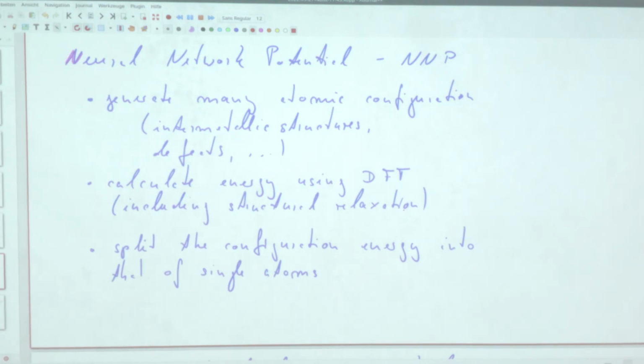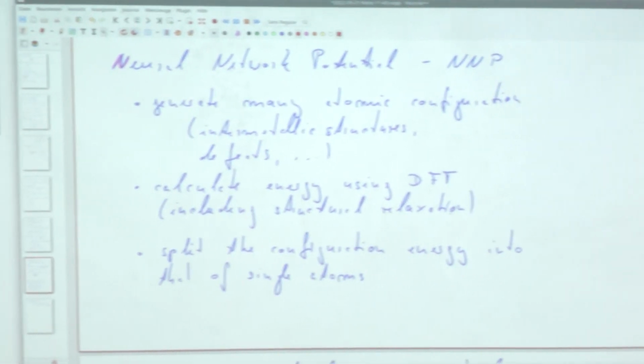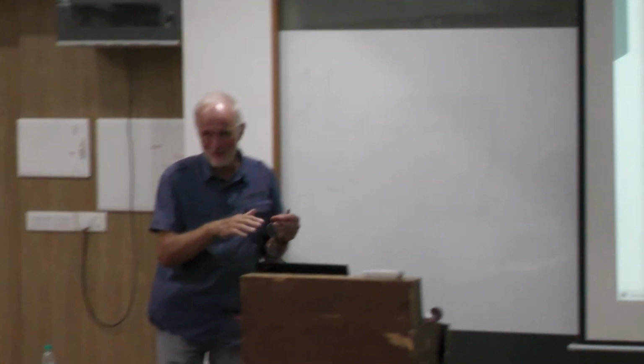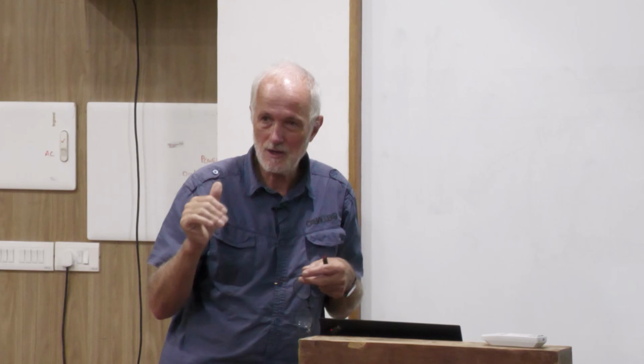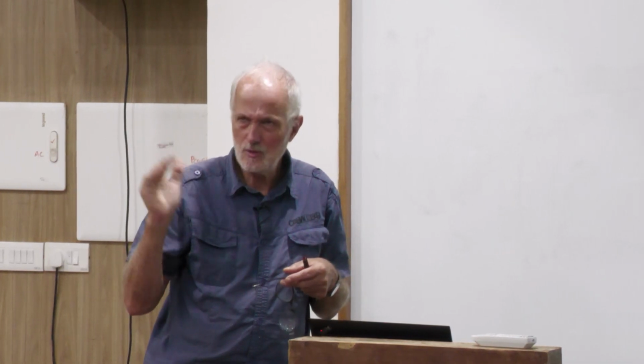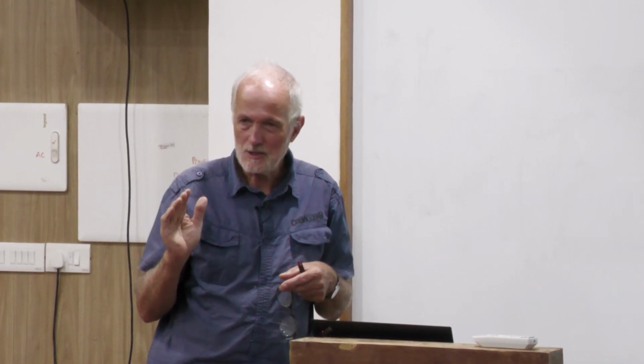Including how do you make that if you want a copper aluminum? Shall we create the structure like FCC or BCC and then do relaxation, or directly only 2 atoms? No. I will show the example how they actually did it. They used, I think, 990 different structures, all kinds of intermetallics. So I think there's aluminum 2 copper phase, aluminum copper 2 and 3, all these phases.